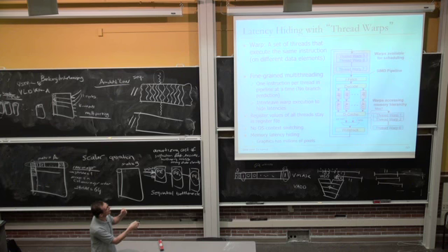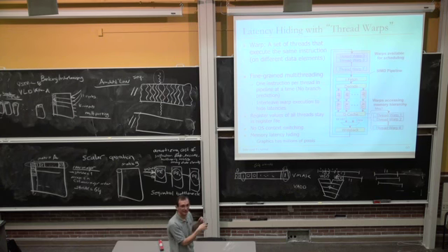What you could do is switch to another thread warp. That's how GPUs actually tolerate memory latency. This is the idea of fine-grained multi-threading. They fetch from different thread warps in consecutive cycles, and if one of them gets a cache miss, it gets out of the way, and other thread warps can continue executing.